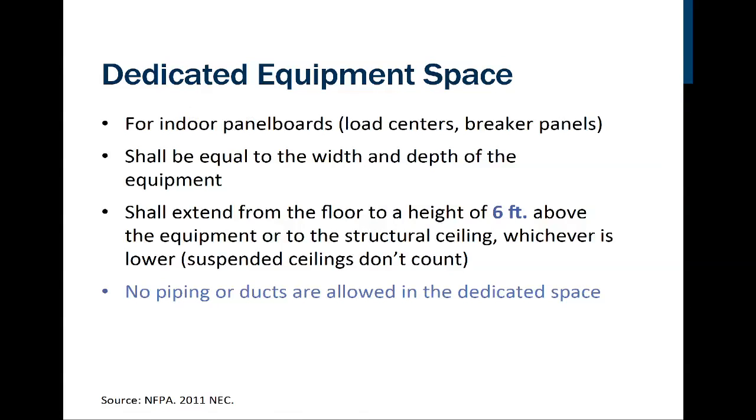So we have to have this dedicated floor space, dedicated equipment space, and it's going to be equal to the width and depth of the equipment. Notice when we're using the word shall. Shall means it's coming right out of the code, and that means you have to do it. No arguing. Okay? Shall extend from the floor to a height of 6 feet above the equipment.